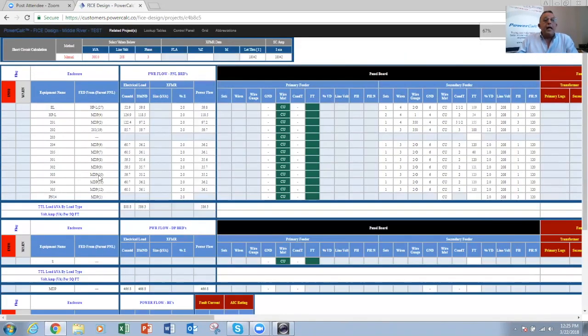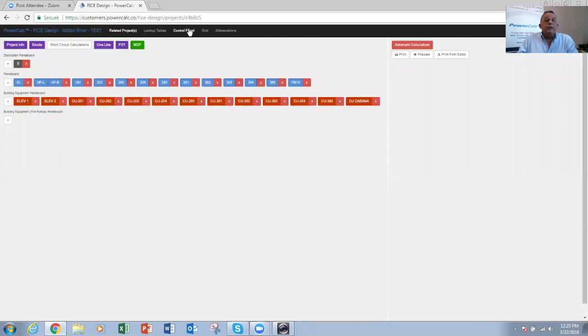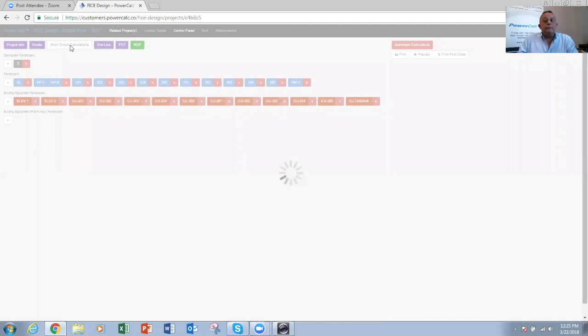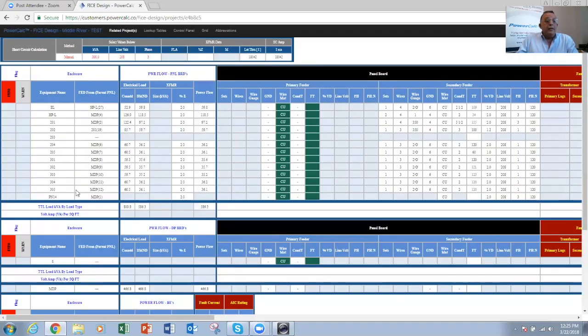All right. You see, it's actually a list of your power distribution system. It starts with the enclosures. These are all the panels that are listed in your distribution system. If I go to the control panel here, these are the panels in the blue, okay? They're all listed in the short circuit calculation form. And then underneath it will be the distribution panel, and then underneath it will be the MDP. Throughout the chart, it will show you the pertinent information that is needed for the short circuit calculations, and then it will go ahead and calculate the AIC rating associated with these particular panel boards and distribution panels, okay?